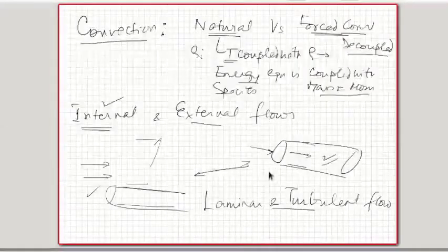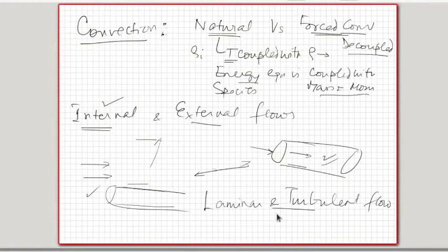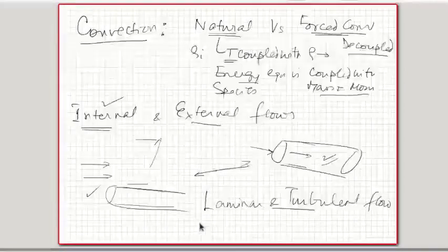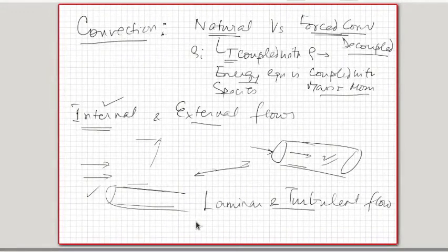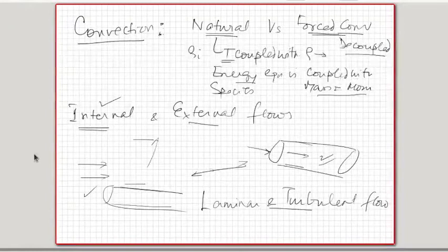flows of different nature. In laminar flows, the flow is dominated by viscosity, and therefore any disturbances that are introduced into the flow are completely consumed and mitigated by the presence of viscosity, so the flow remains smooth. Whereas in turbulent flow, the disturbances are introduced to the flow, either by the surface or because the incoming flow has such disturbances, maybe because it is driven by a fan which is causing the disturbance. Any fluctuations introduced in any of the variables, in the case of laminar flow, because the viscosity is present, it damps out all of those and the flow becomes smoother. Whereas when the flow is not stable enough, the viscosity is not strong enough to damp those out, then these oscillations grow and the flow becomes chaotic, and eventually it's called turbulent flow.